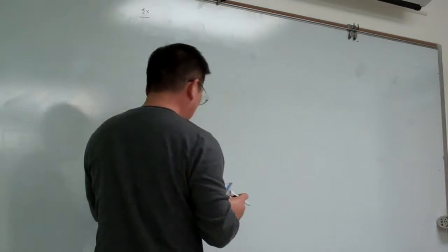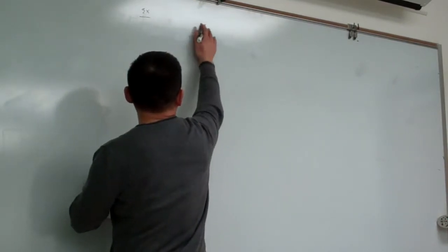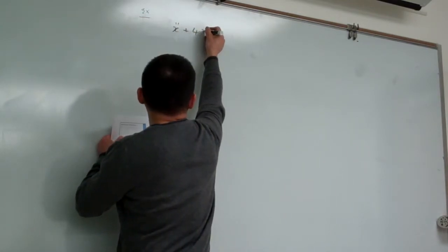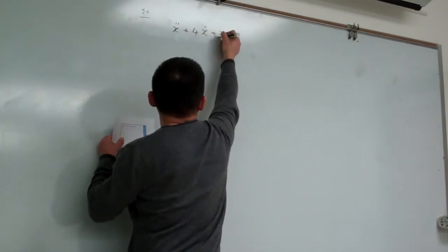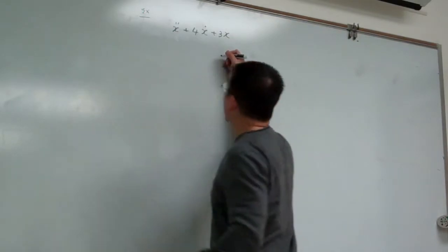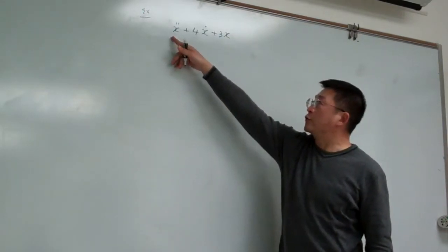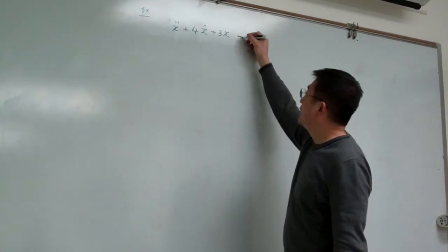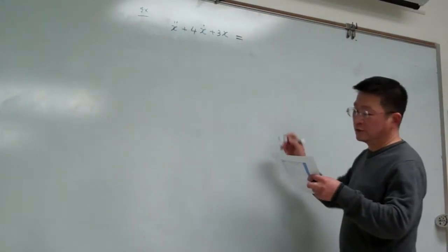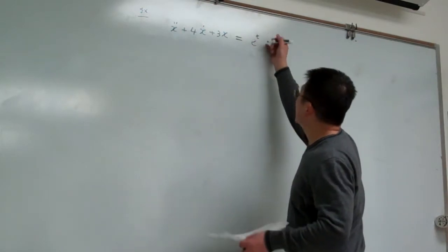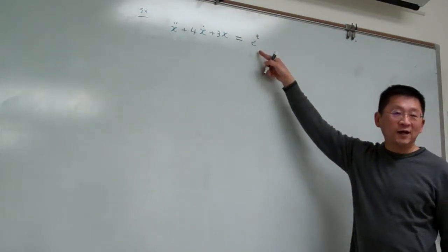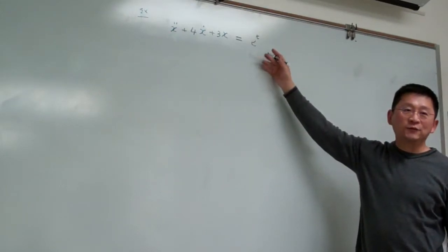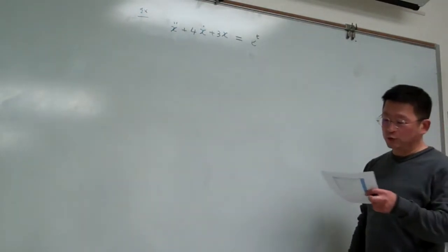So I will give you certain dynamics, say x double dot plus 4x dot plus 3x, okay? That means m equal to 1, c equal to 4, k equal to 3. And this one I say is equal to e to the t. So that is a very weird force excitation, but for exercise, I simply adopt this one.